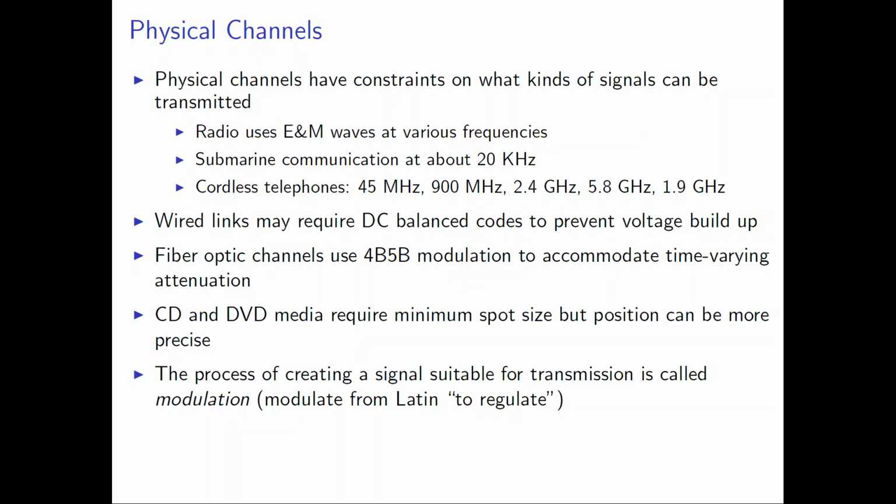So now give me one modulation that can solve this problem. Let's say amplitude modulation, basic amplitude modulation. When 0 comes, make the amplitude of this electromagnetic signal low. When 1 comes, make it high. Simple as that. The receiver then takes the electromagnetic signal. If it is low, this means that the transmitter sent 0. If it is high, this means the transmitter sent 1. It's as simple as this.